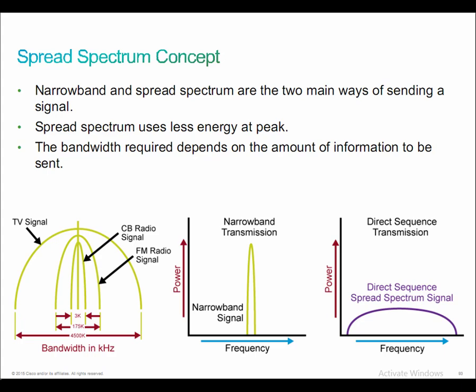The only thing that you cannot control is the interference level of the medium over which that signal is being transmitted. And many devices might be using that same frequency range or even that same band of frequencies. You might even have some wider band applications that might be using a range of frequencies that would include the frequency that you're using specifically in your environment. So one of the main problems with Wi-Fi is how do we eliminate the interference that other devices cause, or how do we mitigate the impact of the interference on the signal that we're sending over that specific frequency.